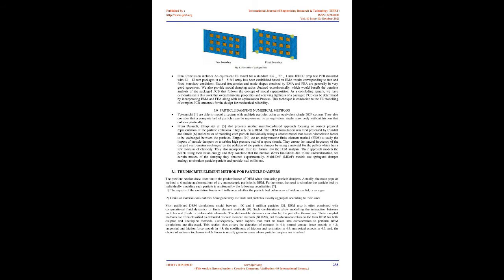As a concluding remark, we have demonstrated in this work that overall material properties and screwing tightness of a packaged PCB can be determined by incorporating EMA and FIA along with an optimization process. This technique is conducive to the FEM modeling of complex PCB structures for the design for mechanical reliability.